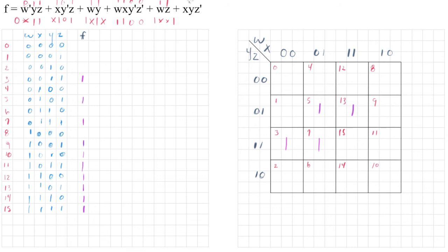We have X, Y, Z naught. So that's on, and that's off. There is no W, so W is don't care. We don't care if it's 1 or 0. The X is 1, Y is 1, Z is 0. So we're looking for anything that ends with 1, 1, 0. So let's look down the column here, 1, 1, 0. Got one right here, 1, 1, 0. And that's it. That's the end of our